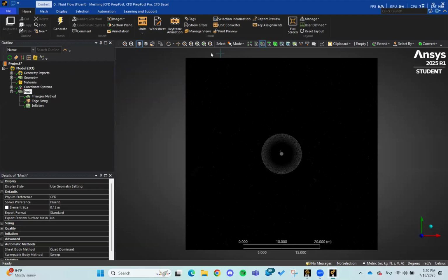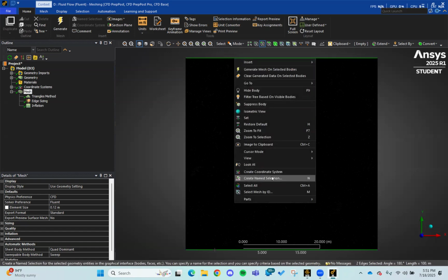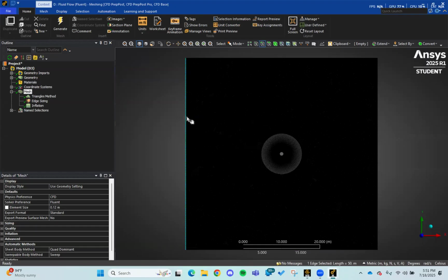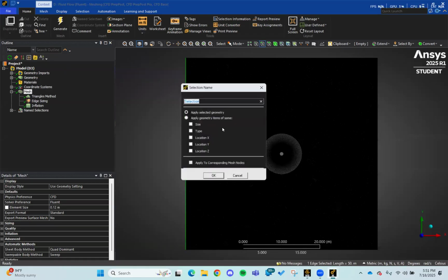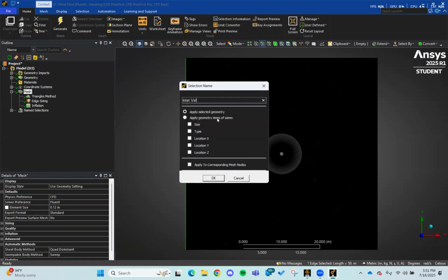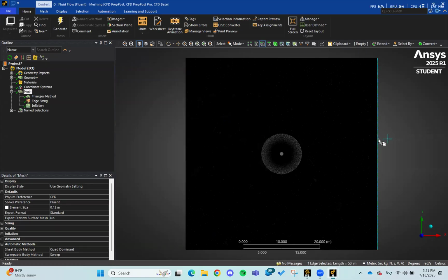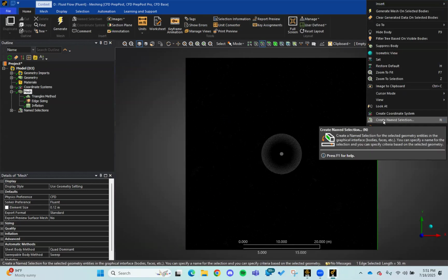I'm going to select edge select over here, and I'm going to start naming our boundaries. So I'm going to name up here and here our symmetry. Create named selection. This is going to be my symmetry. Over here is going to be my pressure outlet.